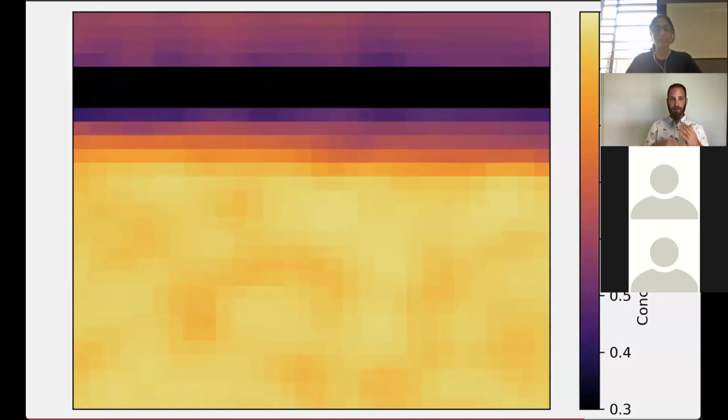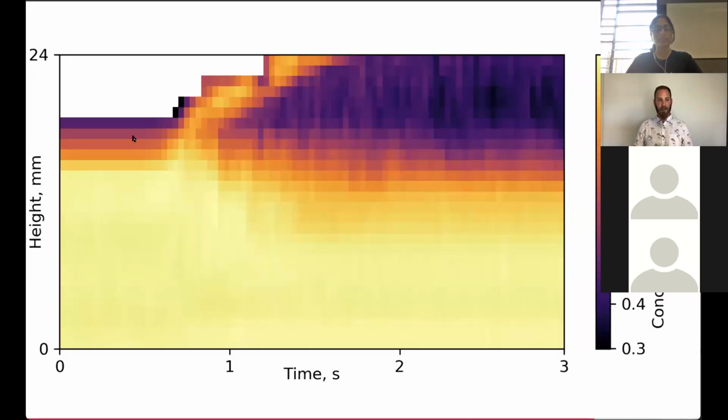And when we do these kinds of measurements, what we can see here is as the flow starts, we start to pick up, so that we have these large particles down the bottom, they start to get picked up and carried over the top. And then we get this flow of large particles slowly eroding into the material. And with this kind of information, we can really start to understand how the system erodes and how that is affecting the flowing behavior.